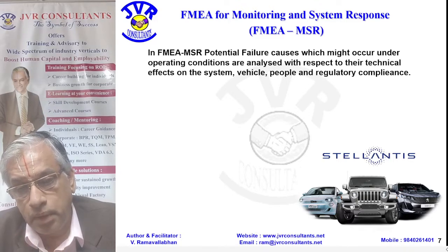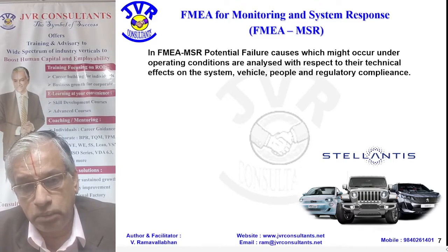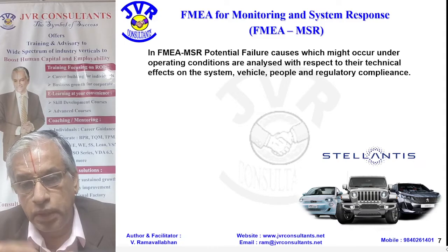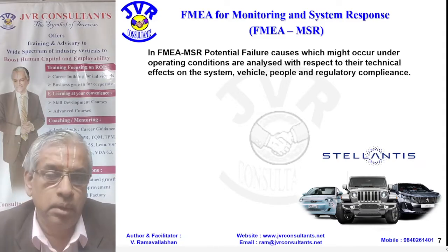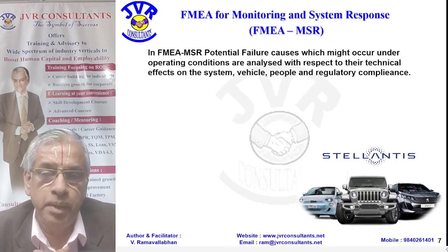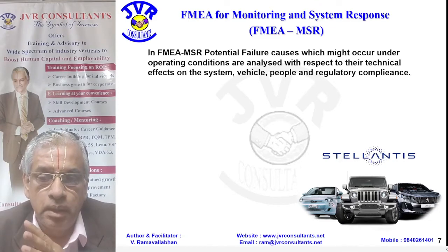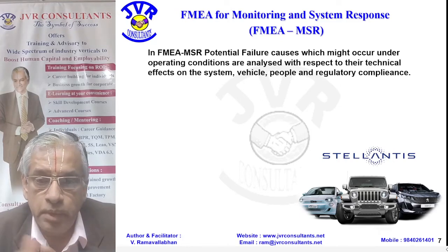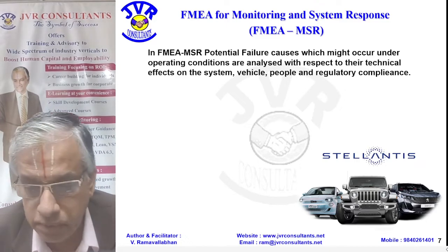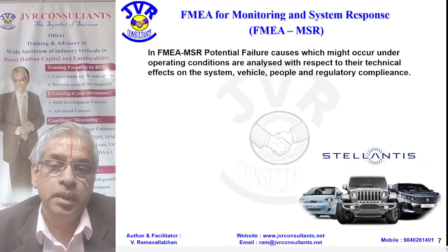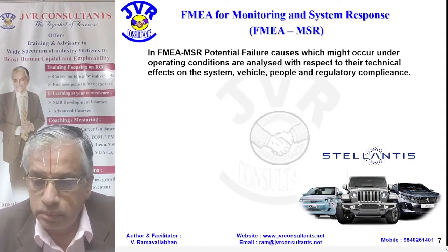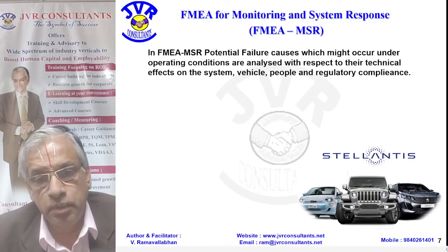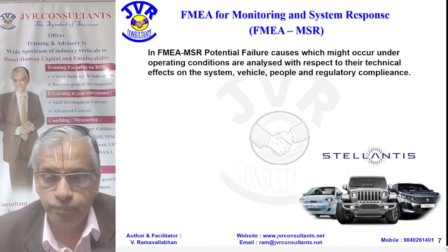Now, here, the product has gone to the customer. At the customer operating condition, what is happening? The end use customer is using it. In his operating condition, how is it performing? If we get some feedback, based on that feedback, we need to look into our FMEA. So for FMEA-MSR, in the AIAG-VDA first edition, they have recommended some format. We can make use of that format. Once you get it recorded, this will become the input for our design FMEA. So our design FMEA will get improved by studying this.